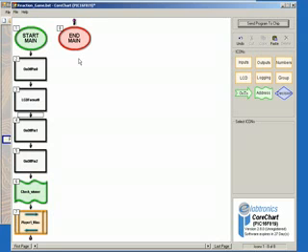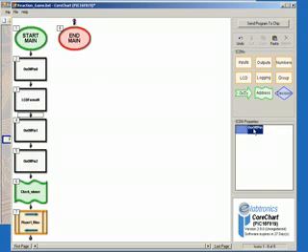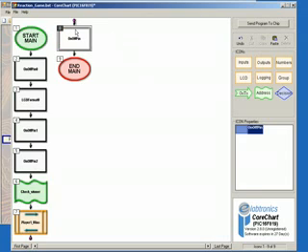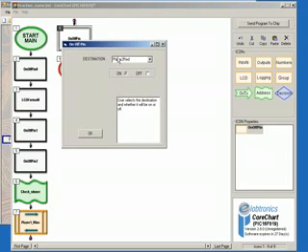We'll now click on outputs again and select on-off pin, and place it by clicking the black arrow at the top of column 2. Double click on the icon to bring up its options, and select D7 yellow LED as destination, and then click off, and then finally click OK.